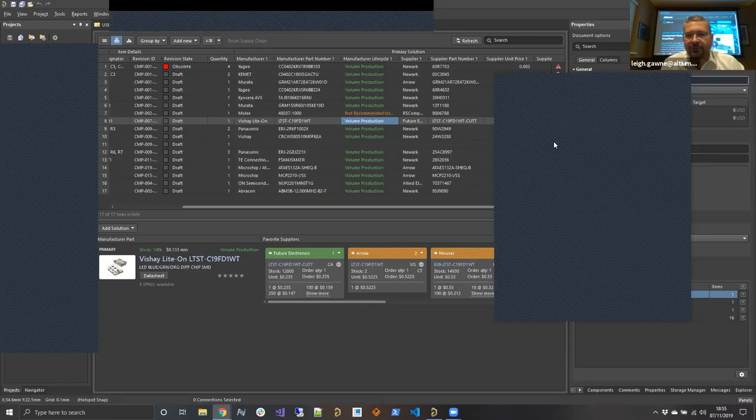Okay, so one question from Vince. Is there any elegant way for Concord Pro to manage a project checked into an external Git server? At the moment, if you've got Concord Pro and you're using an external Git server, then Concord Pro, or Altium Designer, can work with that Git server. So you can still, from inside, commit changes to that project and so on and so forth. And you can make Concord Pro aware that your version control is actually not being done by Concord Pro, but by an external Git server.